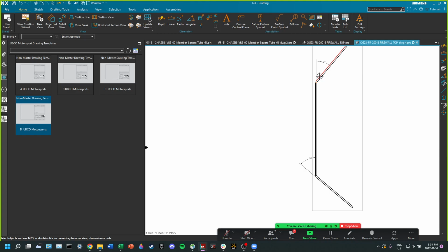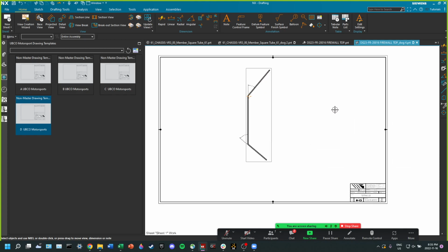So when we're in the shop, it's, okay, all of our dimensions are off of this face. Perfect. So we just turn that face down and then all of our dimensions can be off of that one. It's not, oh, this dimension is off of this face, but then wait, this dimension is off of a face that we haven't machined yet. So then we have to do math to figure out how we need to machine that part. So as you're going through your drawing, think about how it's going to be machined and what datums you're going to want to measure off of.